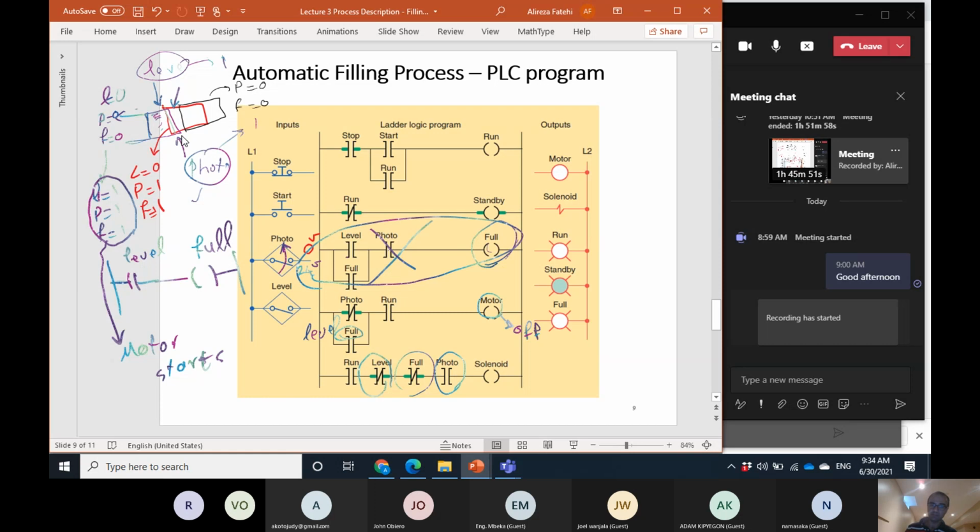This is something that might happen. Somebody goes there for any reason, stops that. At the time that the box was exactly at this point, it is not in front of the level, but it is still in front of the stop. Does it work properly when we again push start? It means, does the motor turn on automatically and then move? Okay, if it does, that's good. If not, we should again analyze that and go through that.